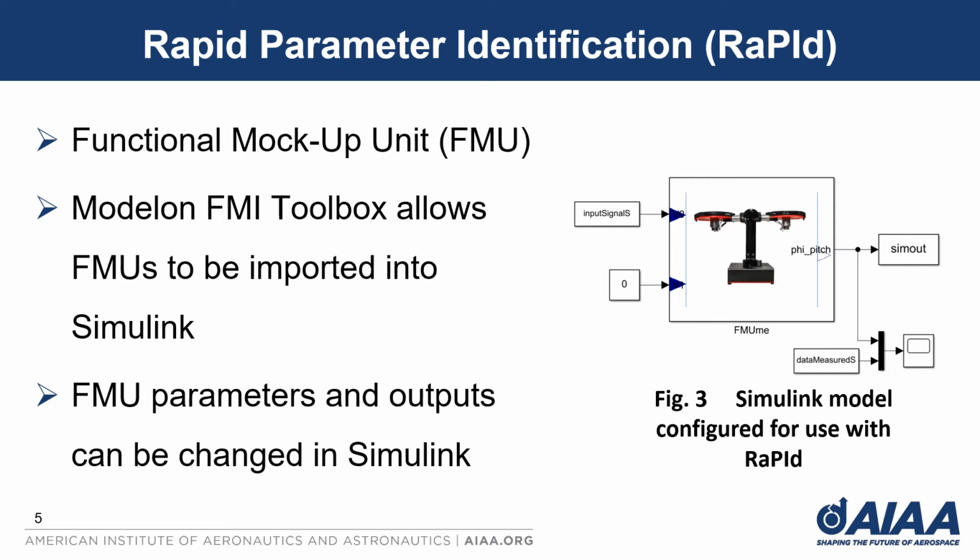An FMU is just a container that adheres to the functional mockup interface standard and contains a model that's compiled as C code that can be simulated as one cohesive unit in Simulink. Using Modelon's FMI toolbox or another FMI-compliant tool, FMUs can be imported into Simulink for simulation. The parameters and outputs of these FMUs can then be procedurally altered while in the simulation environment.